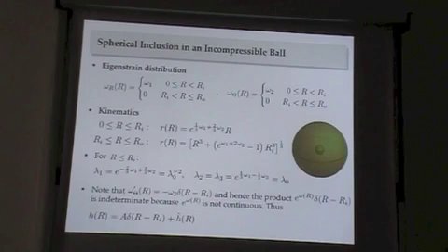Now, to look at an analogy or a nonlinear extension of Eshelby's problem, I'm going to look at the following example. I have this big ball, and I don't have any eigenstrains anywhere but in some smaller ball, centered at the same point. Let's say inside, omega r is some constant omega 1, omega theta is some other constant omega 2. And if they're equal, that means I have pure dilatational eigenstrains. But I can solve the problem even if they're not equal.